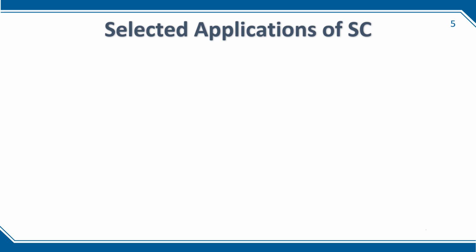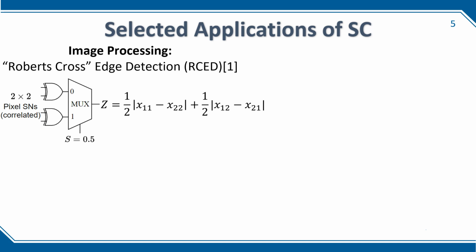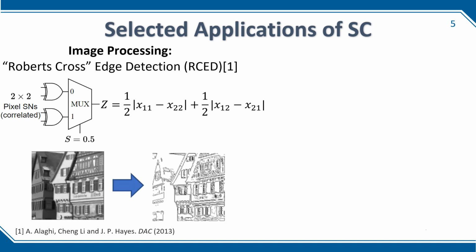There are many exciting applications that are currently being explored by the stochastic computing research community. Here, we will highlight two that are particularly relevant to our current research. The first is an example of a near-sensor stochastic edge detection circuit constructed using no more than 3 logic gates. It is able to produce convincing edges after only a handful of clock cycles, making it extremely power and area efficient, ideal for battery-constrained image processing environments such as mobile cameras or drones.